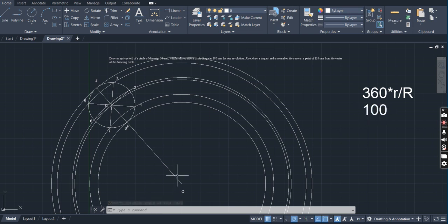Here I want to rotate this line at an angle of 100 degrees. If you give 100 degrees, it will rotate in the anti-clockwise direction. For example, the circle is moving in the clockwise direction, which means I want the line in the clockwise direction. So if I give 100 degrees, it will go anti-clockwise. That's why I use the total included angle of the circle, 360 degrees, and subtract this amount: 360 minus 100 gives this angle.